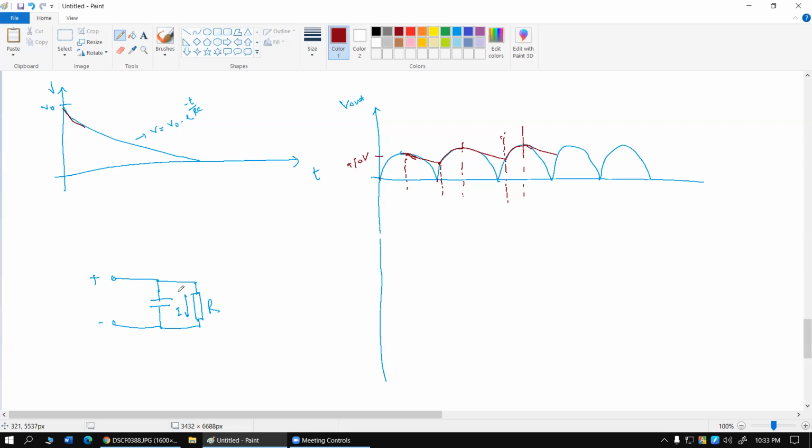But currently, by using the capacitor, we could lift up the lowest value to a much higher value. Look, earlier if we didn't use the capacitor, the lowest supply voltage would drop down to 0 at some point. But whenever we have used the capacitor, the resistor is enjoying the voltage variation, that is this brown line that I have drawn.